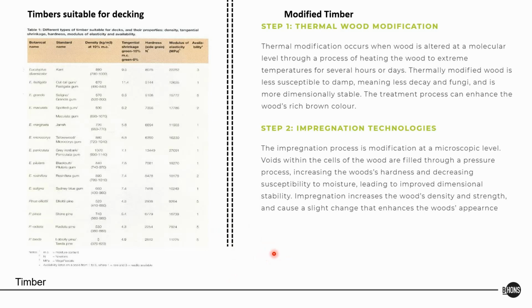They use pine, normal pine, and they put it under very high pressure, high heat conditions, where they actually change the molecular structure of the timber. So it becomes more of a hardwood. And in the process, they will also impregnate it with resin products, so that it becomes preserved completely.